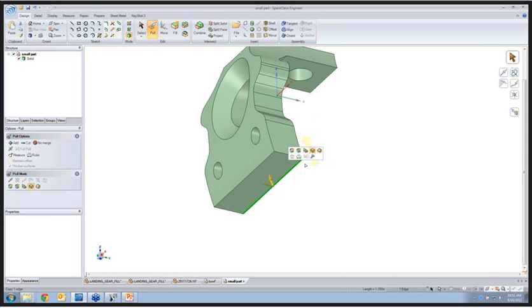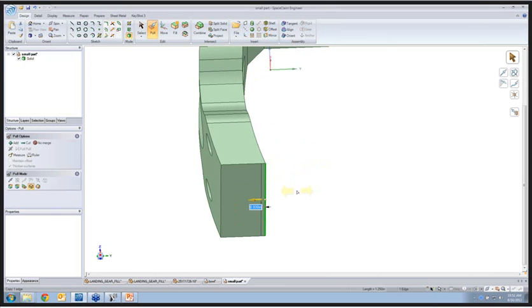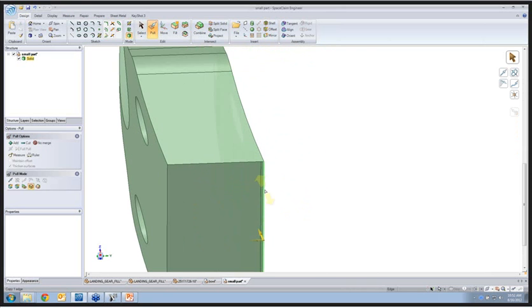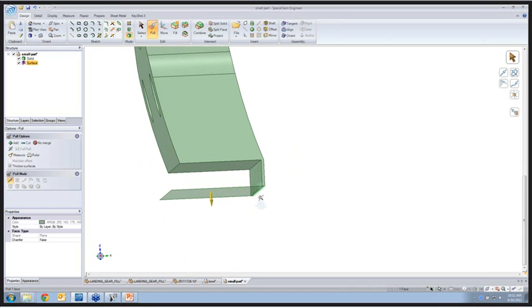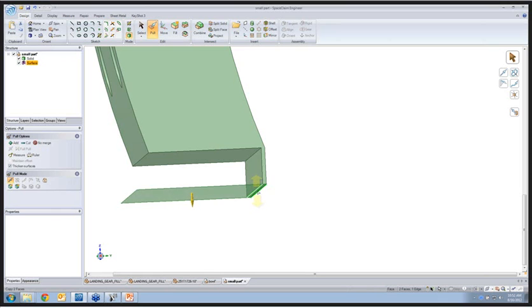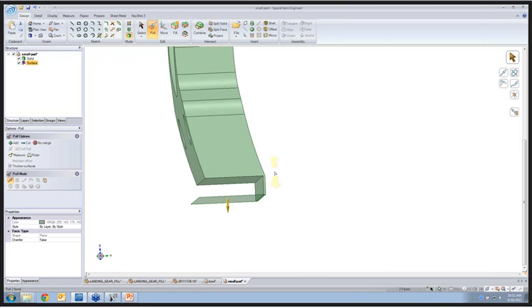The method I want to show you of how to create a fixture in this just utilizes the geometry around, and it's actually called something like dovetail machining. Those of you that are machinists every day are probably familiar with it. You've heard of it at the least or seen it. Maybe you use it all the time. Well, I want to show you in SpaceClaim how you can actually create dovetails on a series of parts put together, and create geometry around here so as to be able to snap off the part from the base, from the fixture itself that I'm creating.